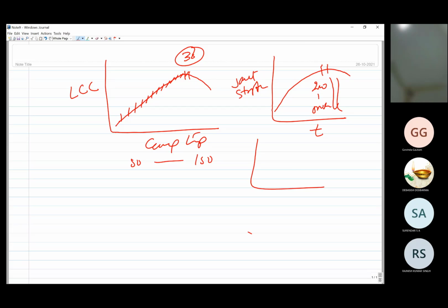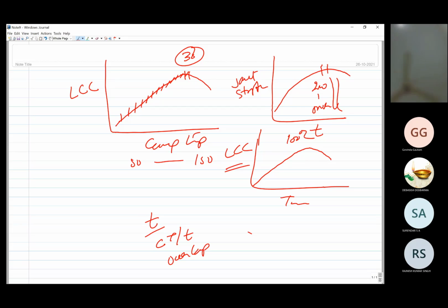And say for a given curing temperature, say 100 degrees centigrade, increasing time will definitely increase strength, and thereafter again for the same reason strength starts decreasing after reaching the peak hardening or peak curing time. Okay, so the load carrying capacity. So this is how, what is important, like the thickness, the curing temperature and time, and the joint overlap length. So these need to be optimized. Okay.